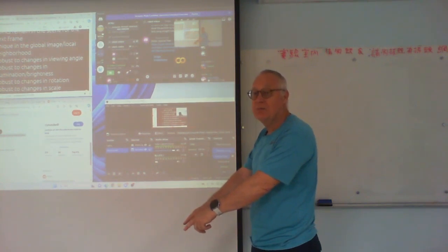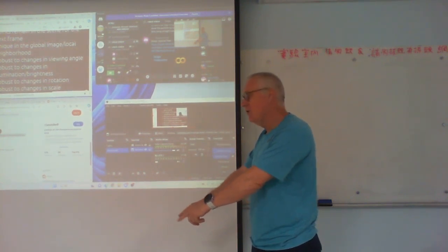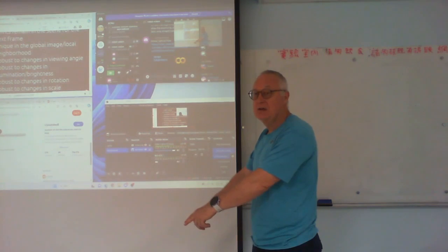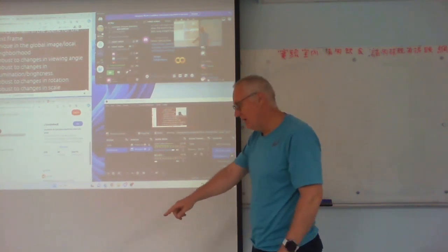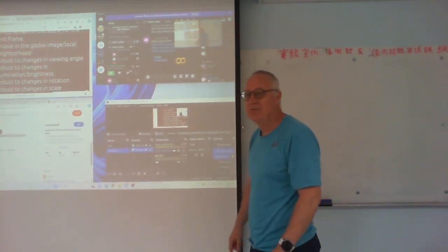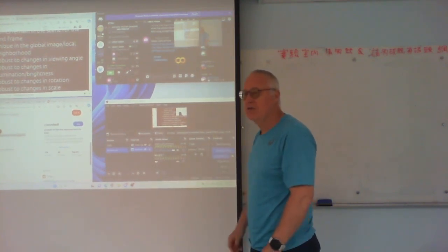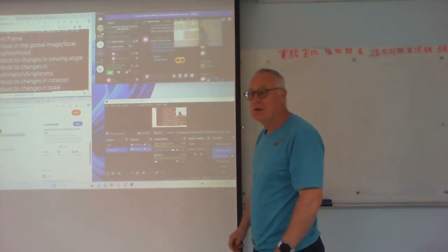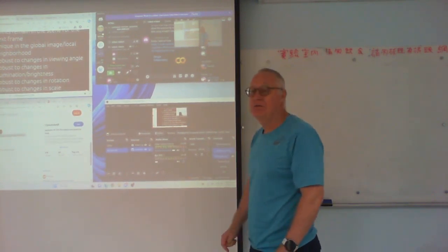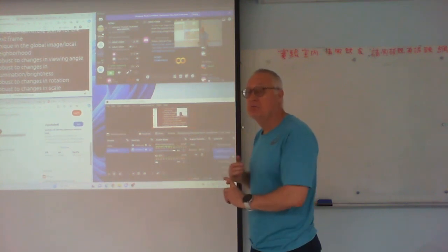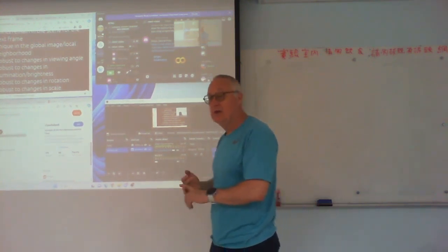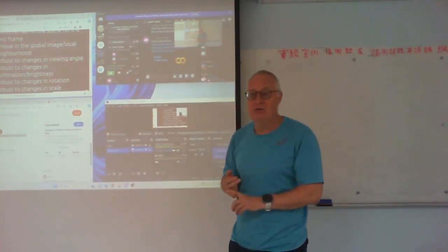They won't be perfect, but they're not really globally unique because each intersection looks the same. They're all like black crosses on a white background. This is for obstacle avoidance, right? This is for any kind of motion estimation, which could be visual odometry and then build up to visual SLAM.